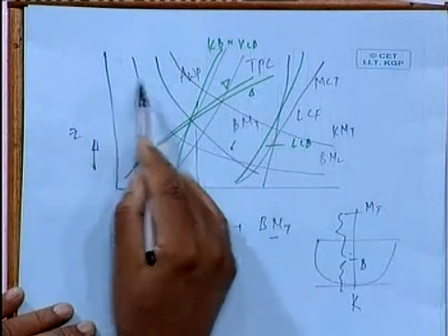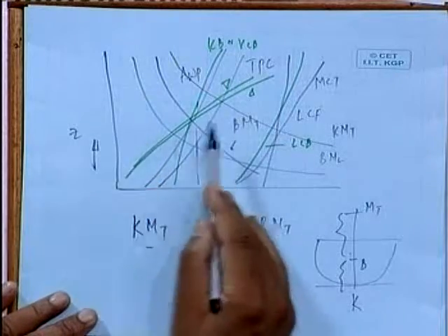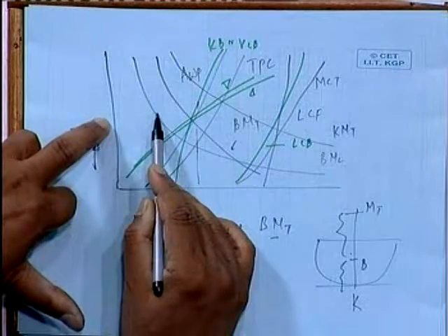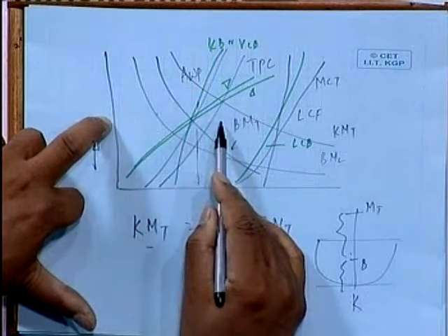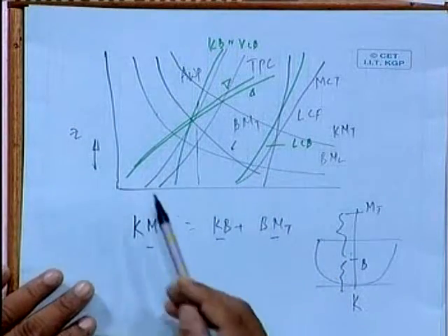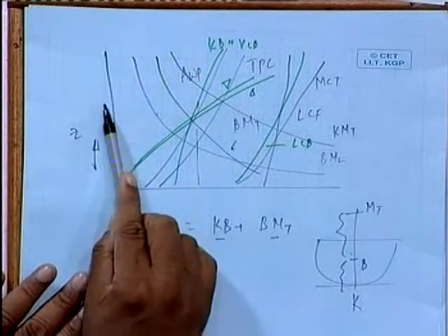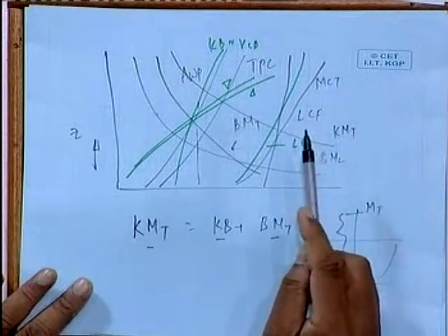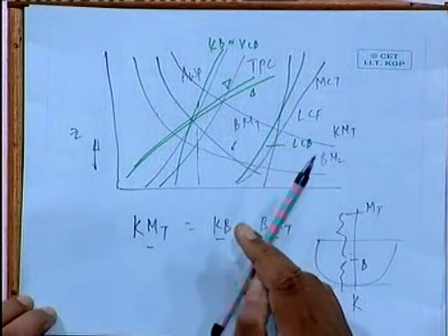These are all various scales. All these plots have different scales. I will show that in the next curve. It will say that 1 centimeter equals so much ton meter, 1 centimeter is so much meter cube, and so on. So if you have this curve and the ship is lying at this line, you can pick up all the values for that line. Say the ship has a draft of 8 meter. For 8 meter, you can find out all its properties. What is my displacement? What is my center of buoyancy? What is my longitudinal center of flotation? BMT, KB, all these quantities.